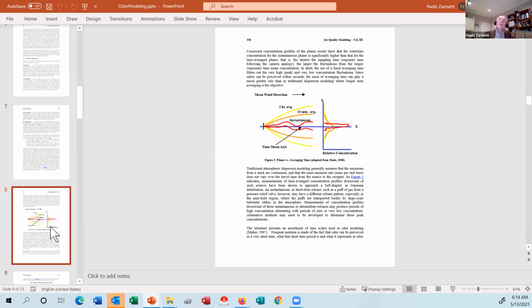So there are simplifications and numerical adjustments that you need to apply for dealing with odors. For example, if you have an hourly measurement of H2S, and the average value is, let's say, 5 ppb of concentration, average in the hour. What you're really interested in is the worst minute of the hour, not the average 1-hour concentration of 5 ppb. You don't know when it happened and how much concentration there was, but you can use some empirical factors.